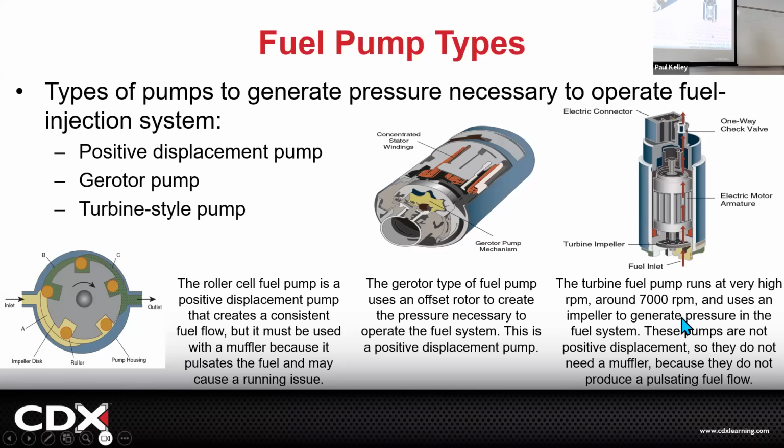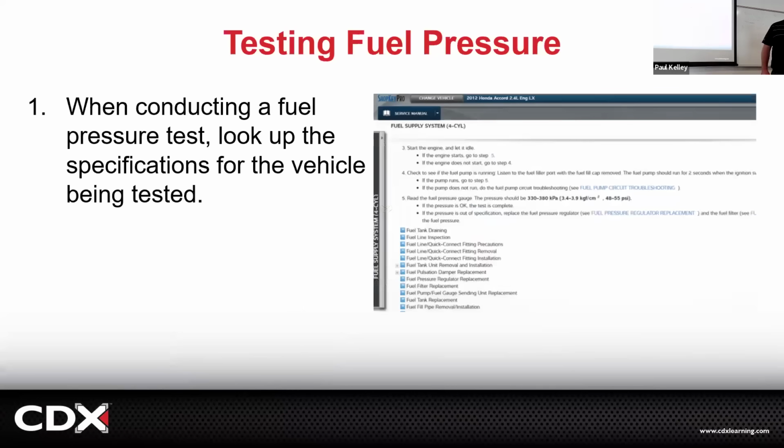So typically the fuel pump should be turning around 7,000 RPM. On the scope, if you were to PicoScope this into a waveform and look at the times, you can actually calculate the fuel pump RPM, but that'd be way geeked out, excessive diagnosis 99.9% of the time. But if it's an unfixable thing that no one can figure out, just know you can tell what the RPM is.